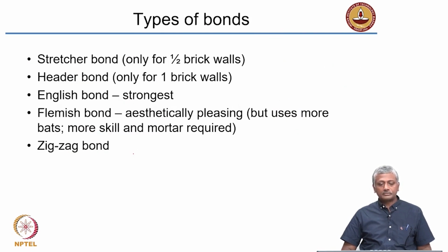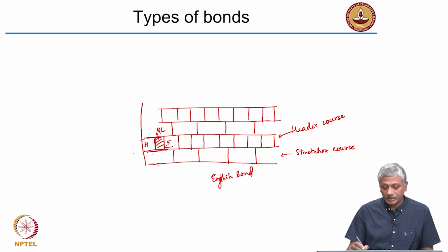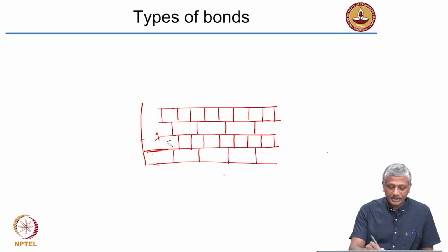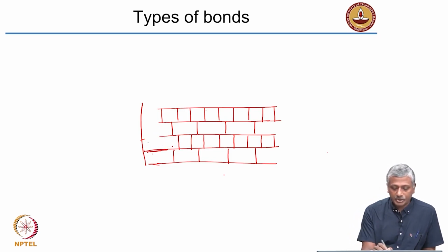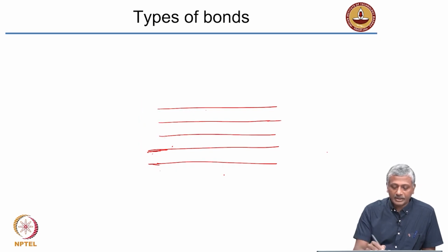Okay, so now if you consider the case of a Flemish bond, in that case we actually get each layer having a stretcher and a header. So let's again draw the same on the same arrangement. Okay. So I want to now have a condition in which each layer has a stretcher and header. So I'll draw again the running length of the wall, that will be much easier for you to understand. Okay.